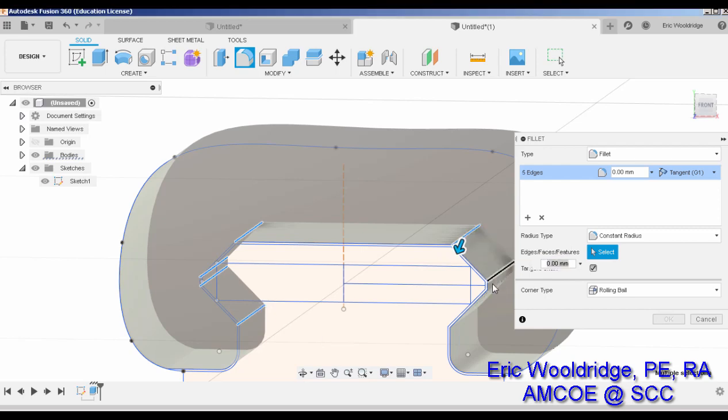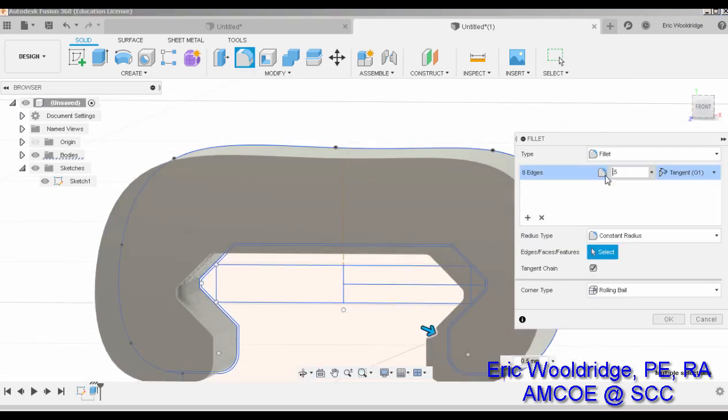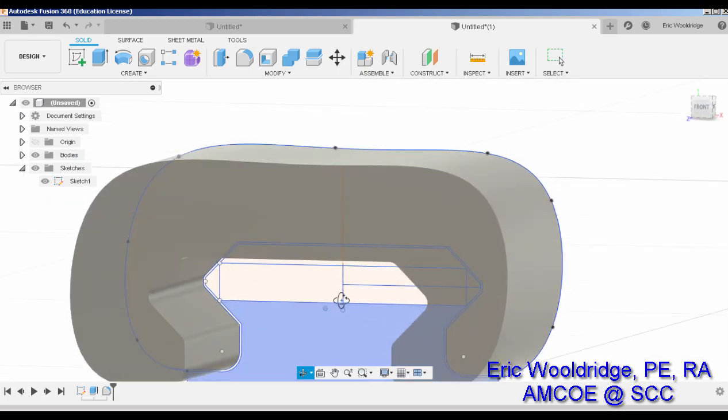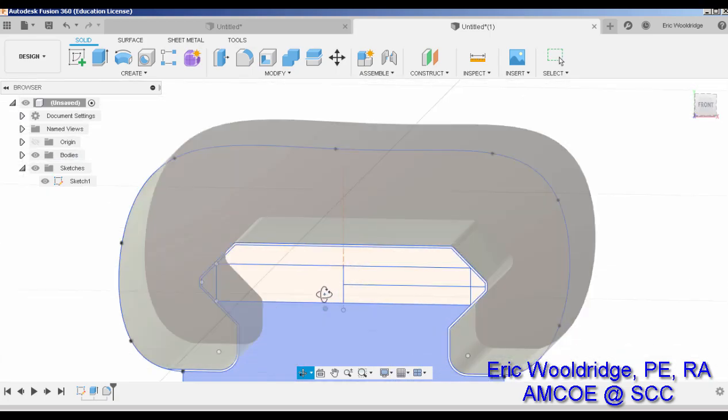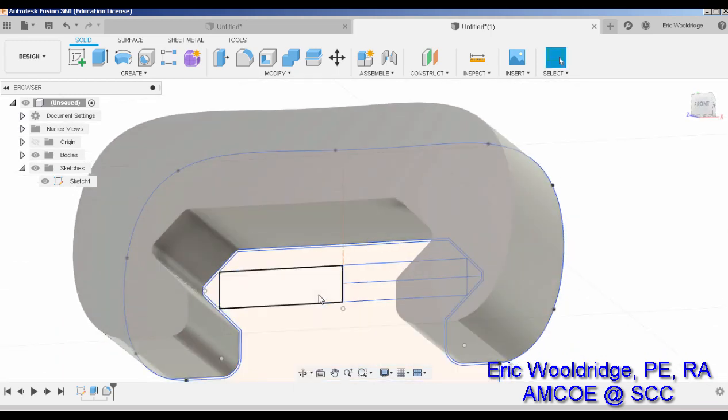right there, there, and there, and there, and maybe setting those to maybe a 0.5 or something nice and gentle, maybe even a 0.8. So they're not too bad, but it creates a little bit of an edging, a little bit of smoothness there at those joints. Again, we always want to avoid sharp corners if we can help it. Alright, so that's this for this one.